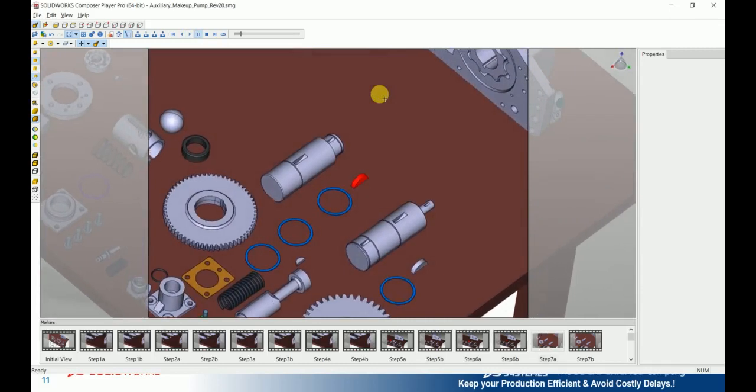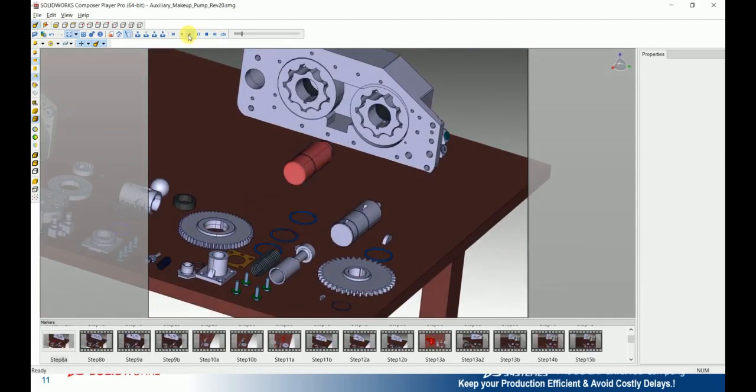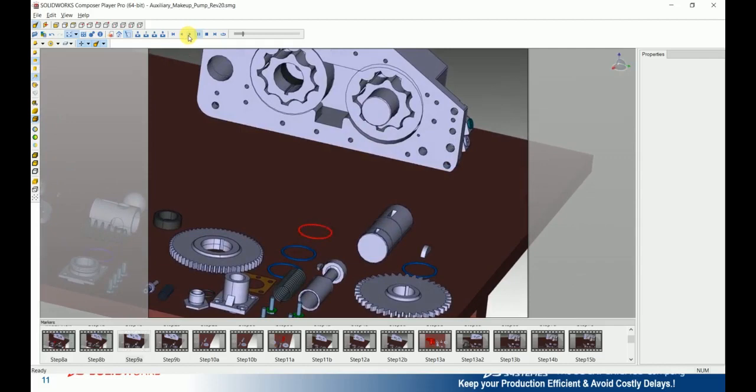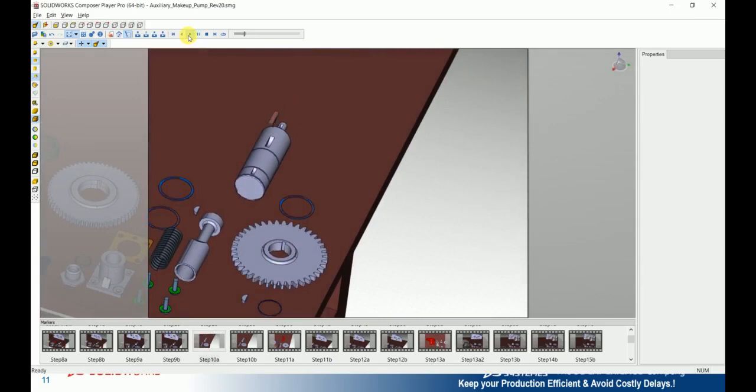And before placing the shaft, I just want to engage a key into the shaft, so that it helps me understand that I have to place a key into the shaft, and after placing the key, take the shaft into the internal diameter of the part, and after that, place the circlips, the bearings, the gears, the shafts, etc.